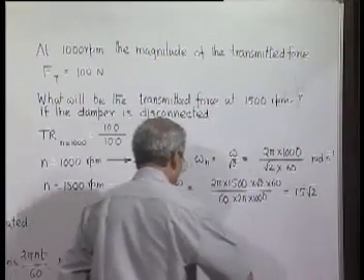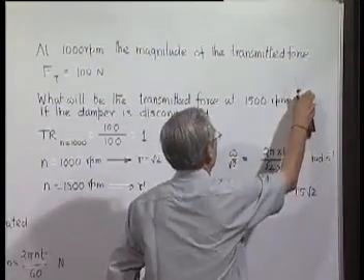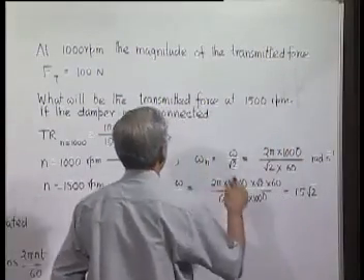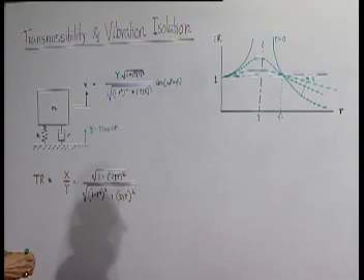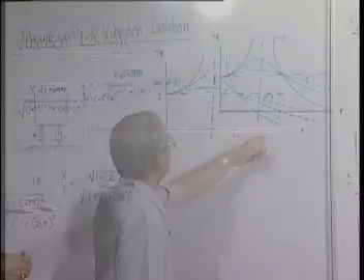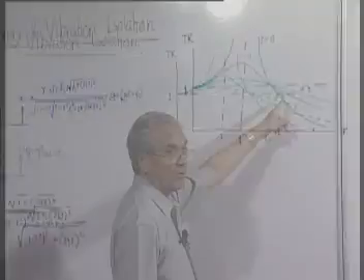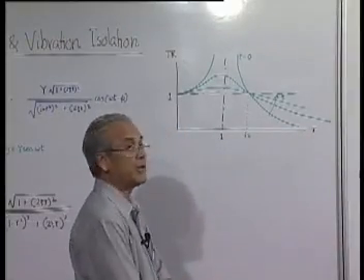In the first experiment, it was not necessary to disconnect the damper because at r equal to root 2, the effect of damping coefficient or damping factor is not present. It is irrespective of the value of zeta, it is 1. But when you deviate from this, then the transmissibility depends on the damping coefficient, information on which is needed.